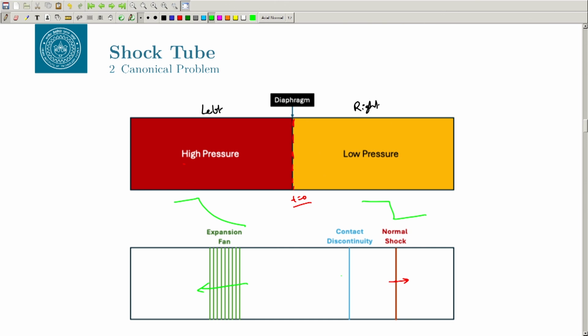Without going into the detail, let us get back to the CFD perspective, that we want to simulate a high discontinuity. That is what the shock means in the CFD course. When you go to gas dynamics, you can look at some other thermodynamical features, what happens to the pressure, temperature, energy, entropy and so on and so forth. But here, from the numerical perspective, we have given a very high jump, and this kind of flow is also called the Riemann problem, the Riemann condition. If you want to represent it, the condition is like this. This is very high pressure and this is very low pressure, this is PL and this is PR, and this is my 0 line. Because of that the shock is forming.